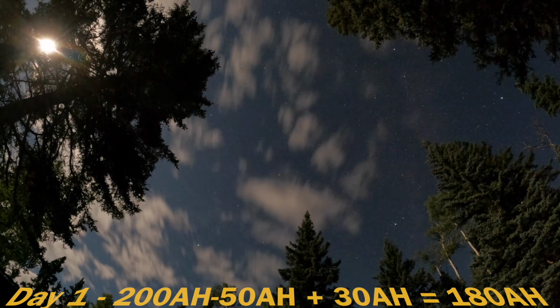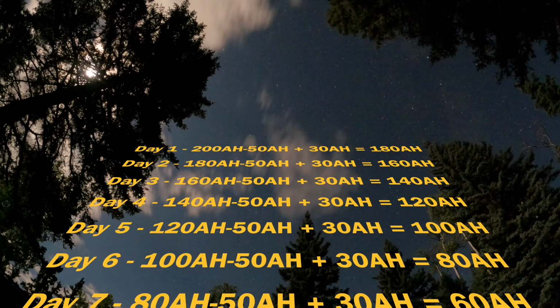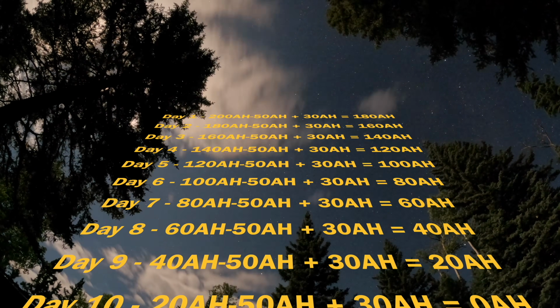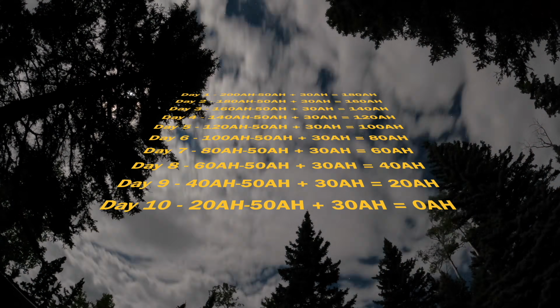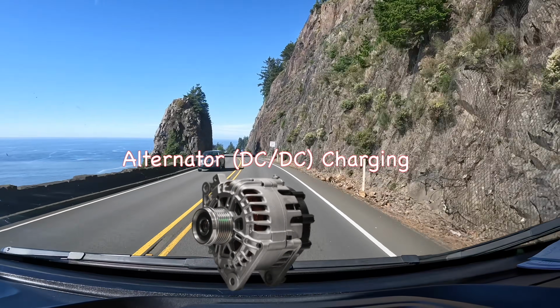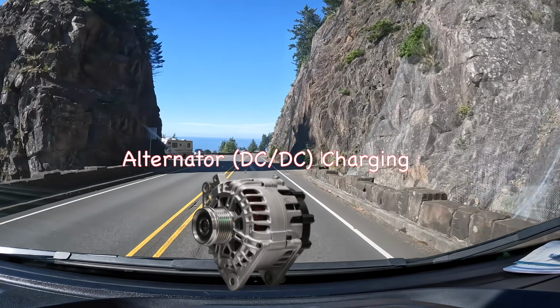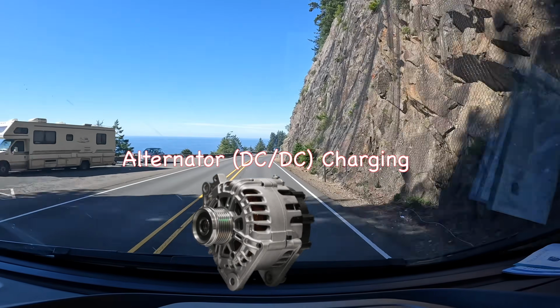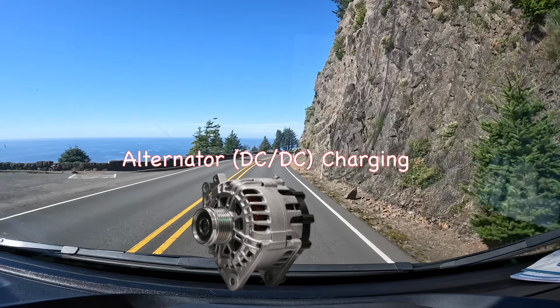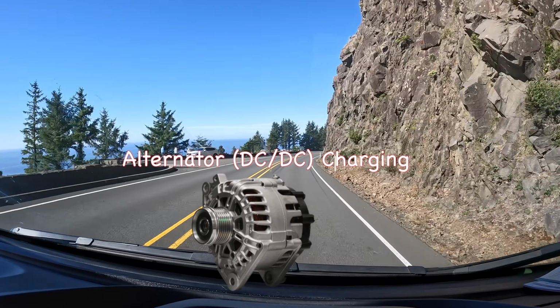With my 200 amp hour battery bank and 50 amp hours per day usage, solar panels alone can maintain the system for about 10 days. My secondary charging system utilizes the van's alternator while driving. The alternator produces a substantial amount of power, and like solar panels, this power needs to be regulated to both protect the batteries and the alternator.